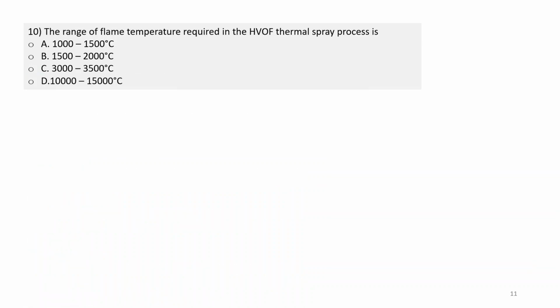10th question, the range of flame temperature required in the HVOF thermal spray process is? Your options are 1000 to 1500, 1500 to 2000, 3000 to 3500, 10,000 to 15,000 degrees Celsius. So the correct answer will be the third option.